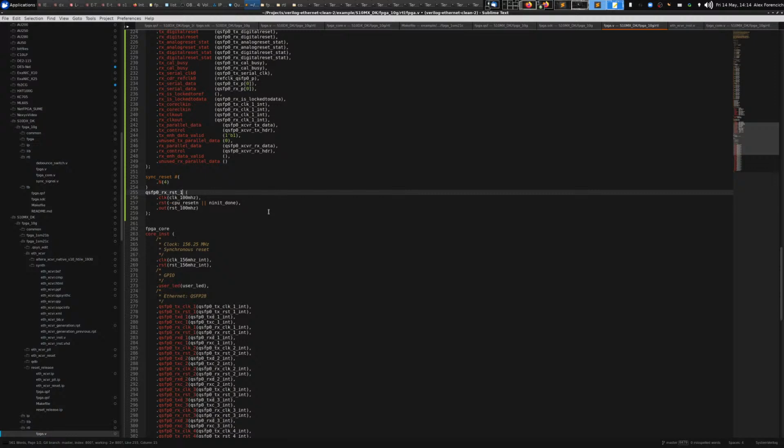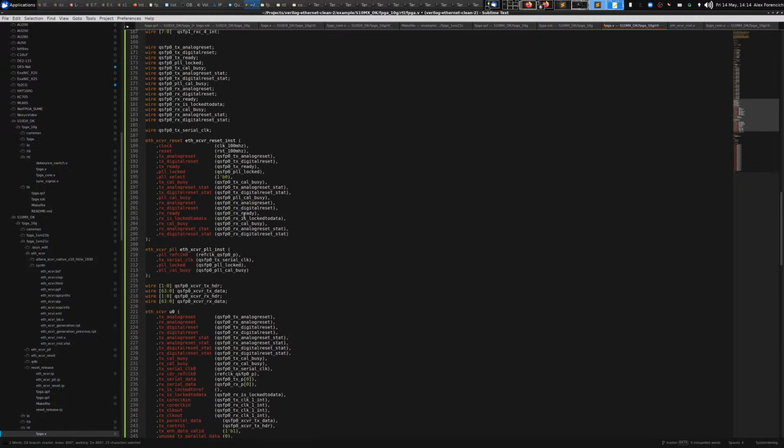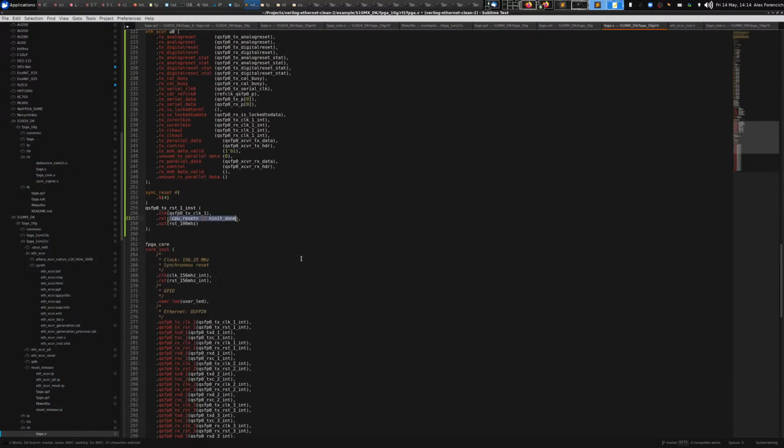Okay. Well, I guess I got the TX now, so I'll start with the TX. So the clock is going to be the TX clock, right? All right, and then I'm going to reset when one of the outputs from this reset controller is indicating that it's not ready. So this is a TX, so I need to look at the QSFP0 TX ready signal. Okay, and I'm resetting it when it's not ready. And then this provides the RX reset. Oh, and then these are going to be int and int.